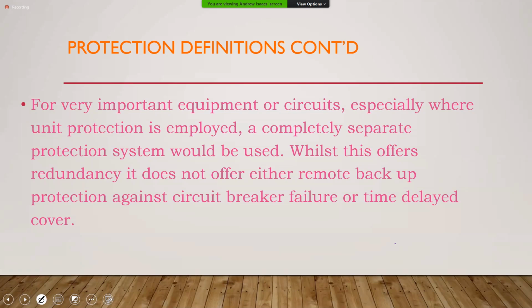Some relays require both a voltage and a current input to operate. For example, your distance relays measure the distance along the line by comparing the current and the voltage. So what they are measuring is impedance.